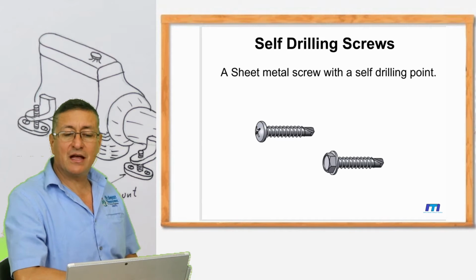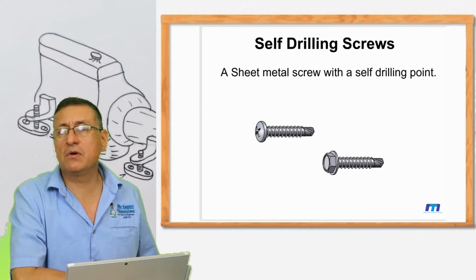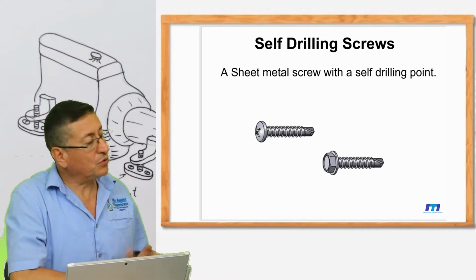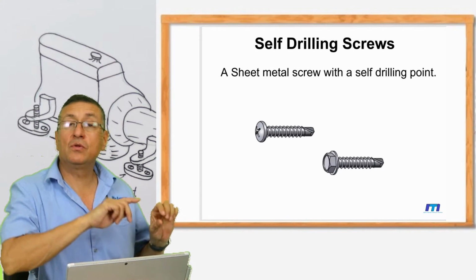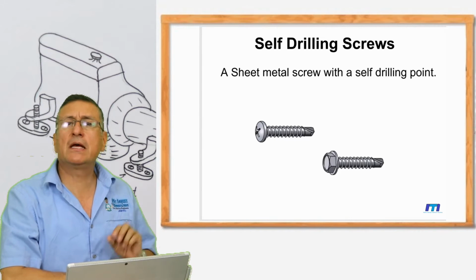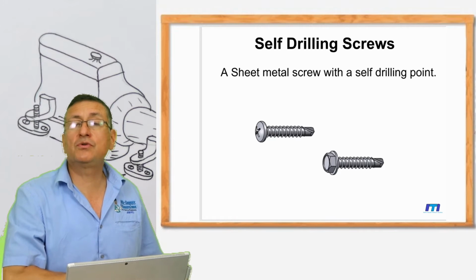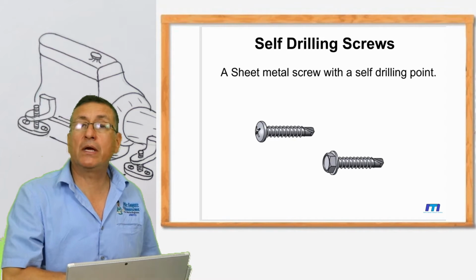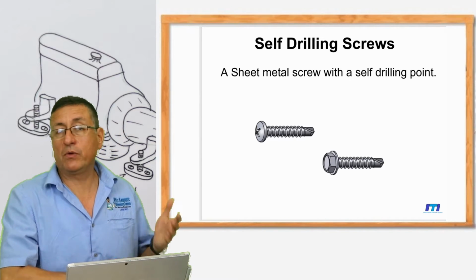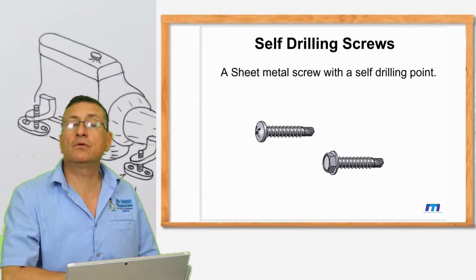And this one, the self drilling screws, are used in a lot of air conditioning equipment. Water makers, they use those screws because they do the hole and immediately enter. It's for sheet metal, and once again, you can use those screws if the screws are marine grade 300 series: 300, 304, 316, 302.